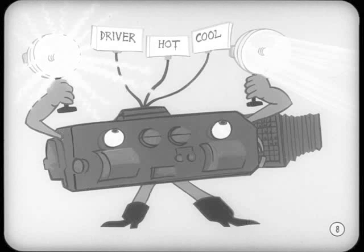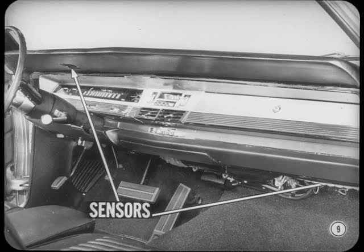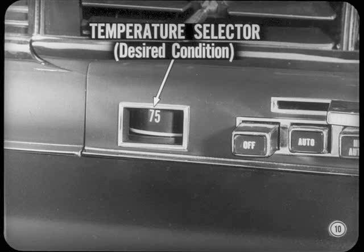The temperature control is taken almost completely out of the hands of the driver and occupants by 3 small electrical regulators. One reacts to the selections of the driver, the others react to the existing conditions. 2 of the regulators, called sensors, pick up the temperature of the air inside the car and the air entering the car and change these temperatures into electrical signals. These are the existing conditions. The 3rd regulator, called a temperature selector, also generates an electrical signal. But this signal depends on the setting of a comfortable temperature. This is the desired condition.